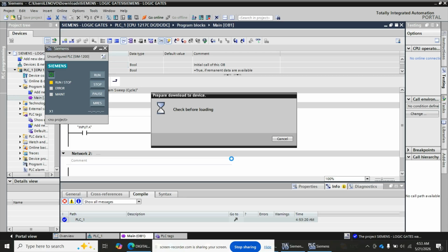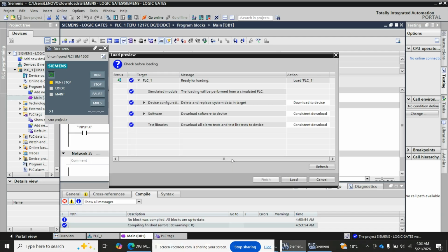But I hope you have understood how we arranged the normally open and normally closed, and we said the normally closed switch is normally used as an inverter. It is used a lot in stop push buttons and emergency stops. If there's an input, then it cuts the power to the output.